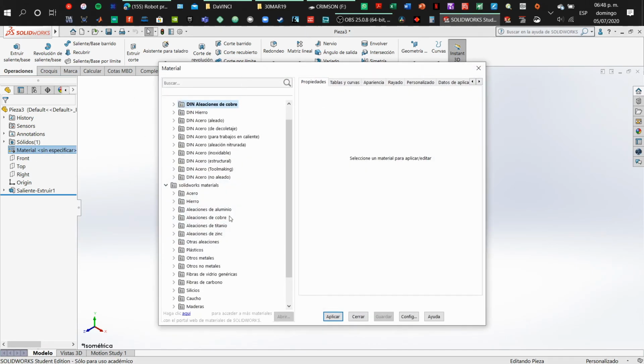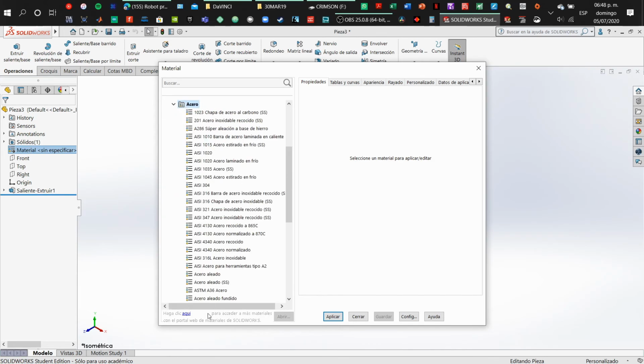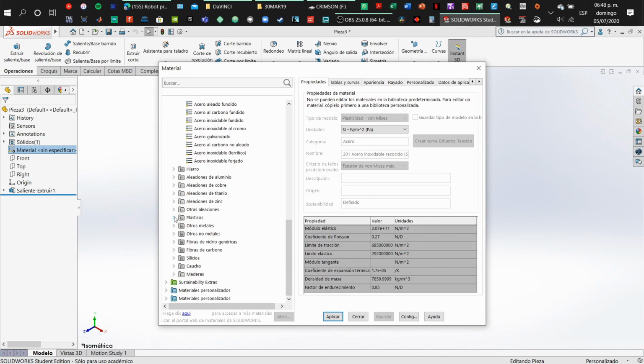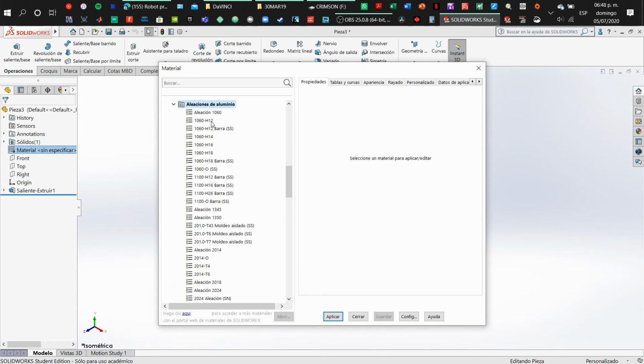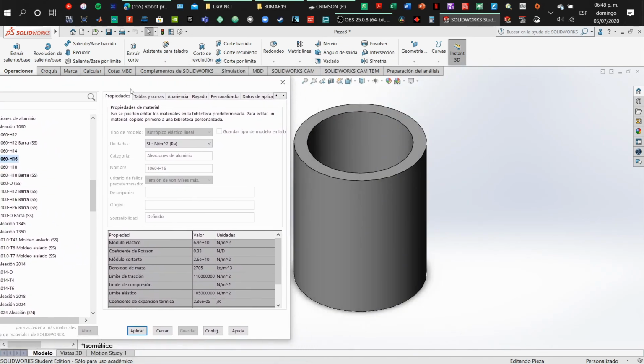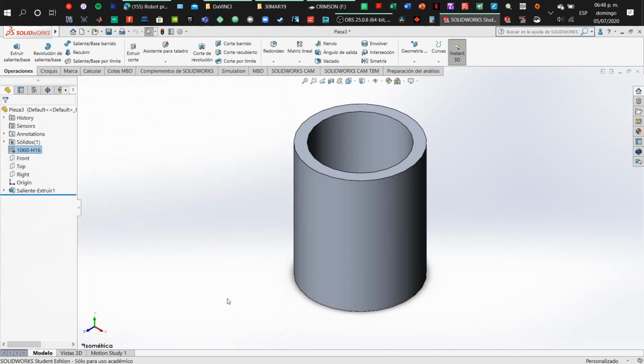And you have created a hollow part. So we can also apply material in the project tree. There's a part where it says material, and you can right click it and add the material, and we can search for steel or aluminum. And what is interesting is that it will have all of its properties. So when you apply it, one, it will change color, and secondly, when we make a simulation, it will take it into consideration.